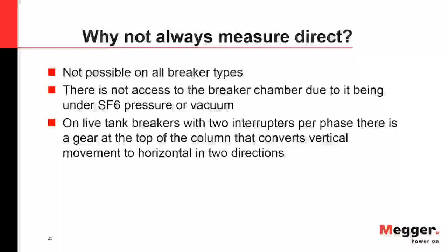And what this does is you can see, from when your main contacts are connected, you'll have a micro-ohm resistance. Then at some point, the main contacts will disconnect, and you'll go to your arcing contact, so you'll go from a micro-ohm to a milliohm measurement. And then at some point your arcing contact opens up, and you'll go from milliohms up to infinite ohms, or an open circuit breaker. And so this is used to evaluate the arcing contacts on your SF6 circuit breakers.